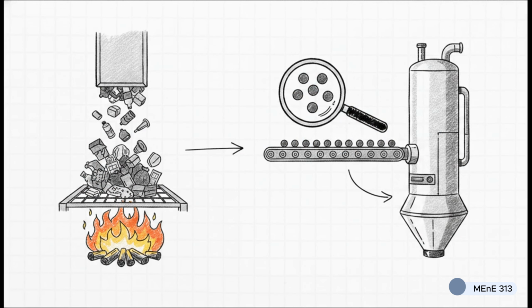Now, if the thermal route is chosen, we don't just broadly incinerate things. We have to carefully, deliberately match the exact technology, from mass burn all the way to advanced gasification, to the precise moisture and heating values we measured in the lab. Gasification, for instance, requires way tighter control over particle size and homogeneity than a standard mass burn grate system.